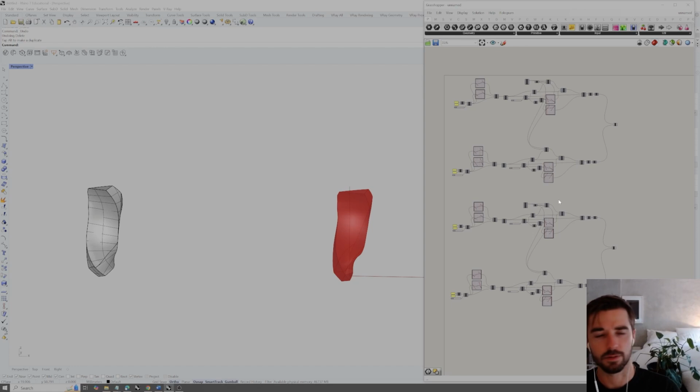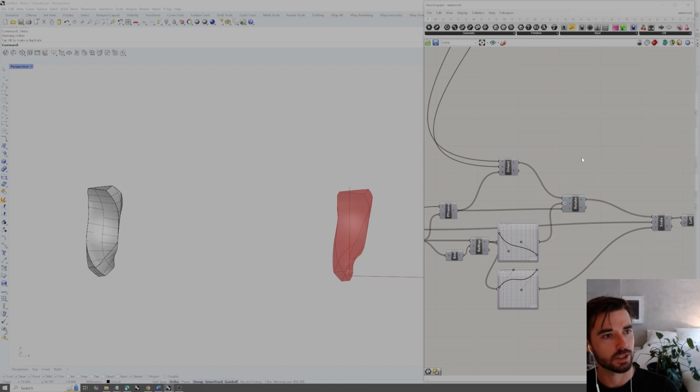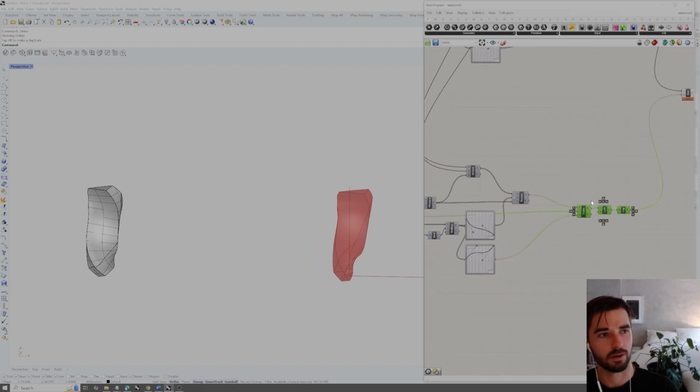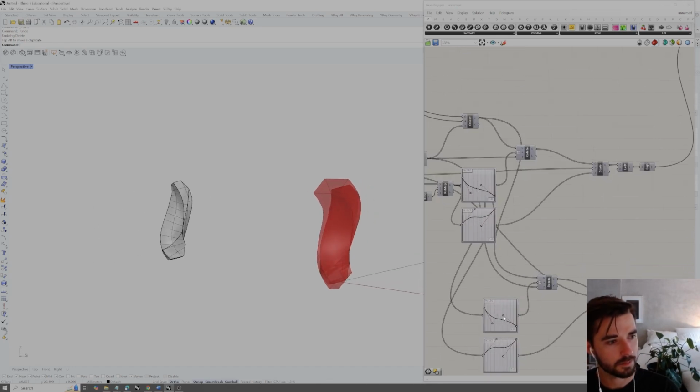Maybe another way actually of doing this so that we can avoid just duplicating, just to kind of prove a point that it's always better to try to build off of your previous work, is going to be to take these rotations and then build a separate set of lofted sections with different rotations and scaling. So what we can do to do that is just take this set, build off of the same base curve, duplicate just the rotations and scale. Just to double check, we can preview that. And then just adjust the graph mapper alone.